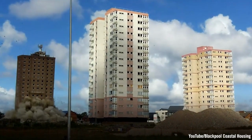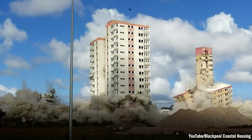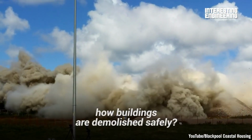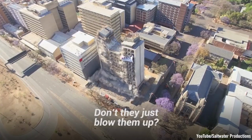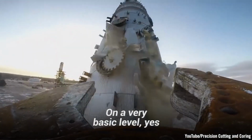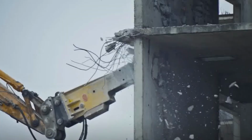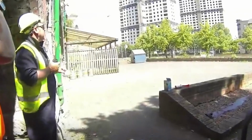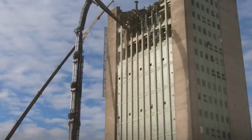Furthermore, in the demolition aspect, structural engineers make sure that buildings are demolished safely and efficiently. Even though demolition is the reverse of construction, many of the same principles and safety concerns apply. The order in which a building is dismantled matters. It poses a safety risk if the wrong structural elements are removed or weakened at the wrong time. Structural engineers help to maintain an optimal demolition process by coordinating the process and the techniques used.